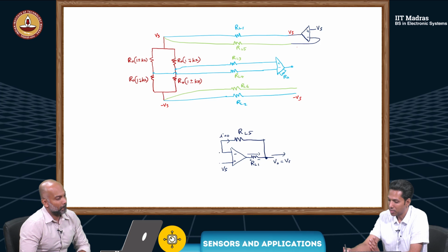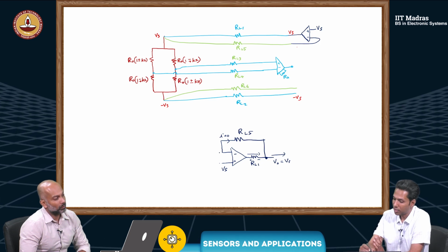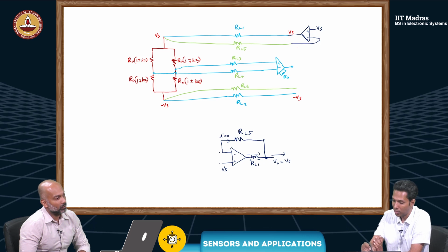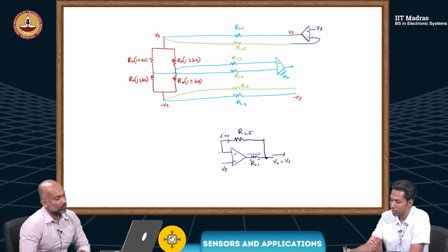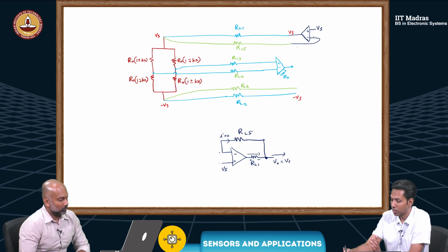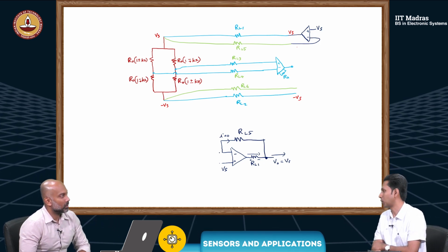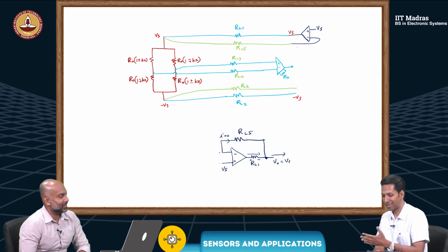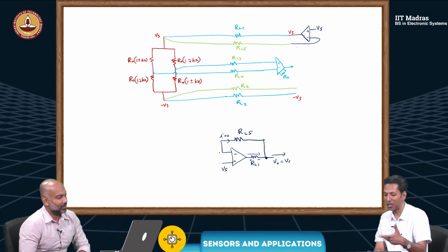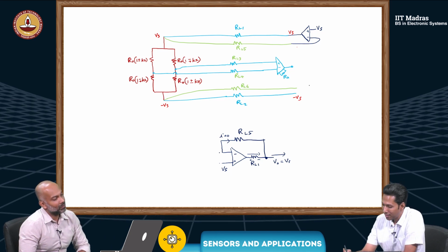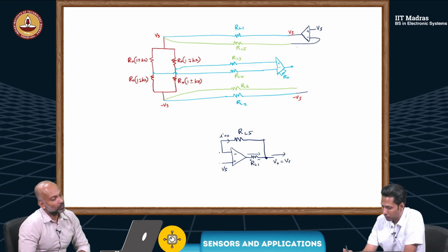So you have Vs here. The one wire that was supposed to be Vs here, I was not sure whether it is reaching or not. I have connected it to the negative inverting terminal. So it's actually forming a voltage follower, except RL1 and RL5 are part of this now. Same thing we'll do for the other side.